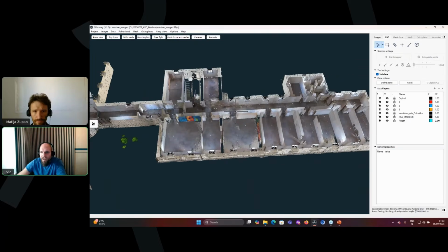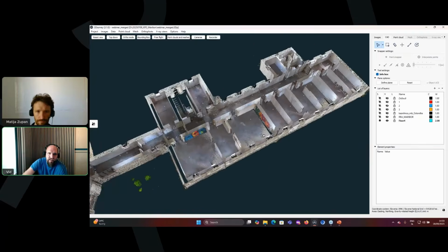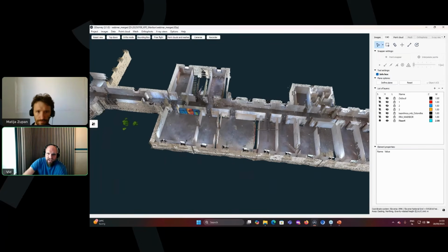Now, the digitalization was done by the institute, but we helped them, talked with them and tried to discuss the best workflow for them. The workflow we came up with is the following. We go into CAD, and here we will extract the wireframe. It is important that the wireframe itself is made out of perpendicular lines, so that the whole BIM model will be made with such perpendicularity. Now, how will we achieve that?